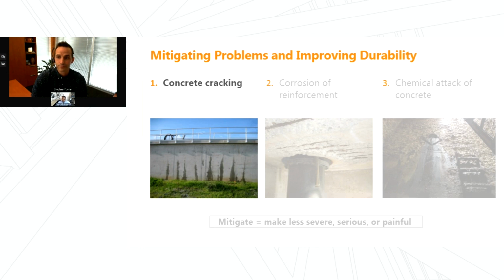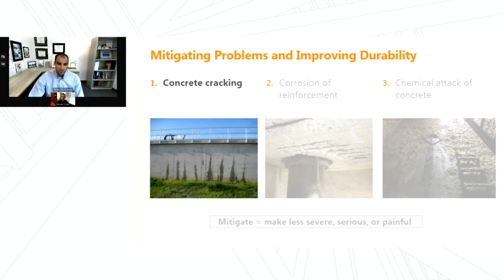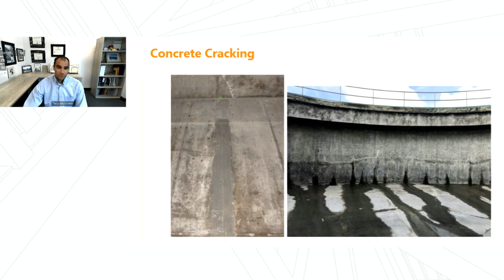Great. Thanks, Stephen. Yep. So I get to start off with everybody's favorite topic about concrete, and that's cracking. So got a couple photos here just to kick us off. Photo on the left, we've got an example of some cracking that's been treated a little bit with a coating and also has some efflorescence, so evidence that we've got moisture moving through the structure. And pretty clearly, photo on the right, you can see active water leakage coming through cracks. So definitely evidence of leakage and issues there.